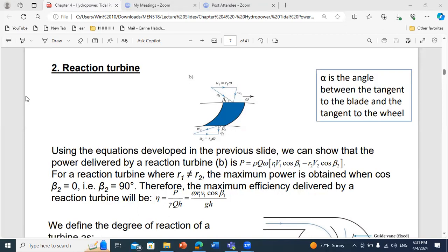First, we need to find the expression of the force F. And second, we find the power by saying that the power is F, which is the tangential force, times the velocity along the tangential direction.